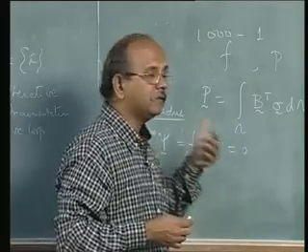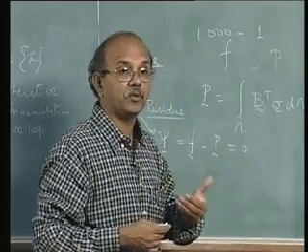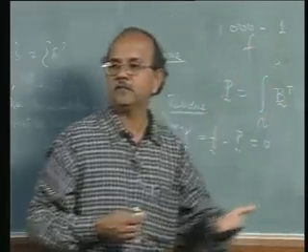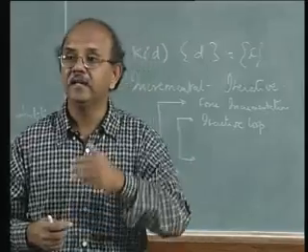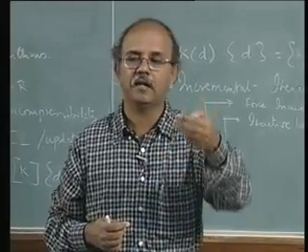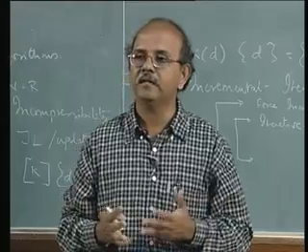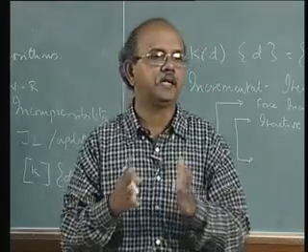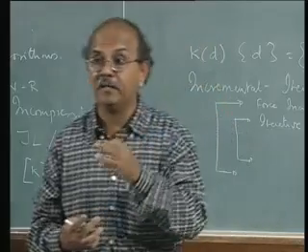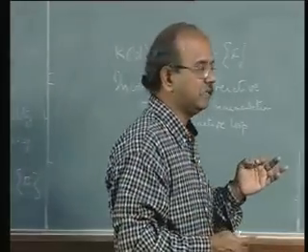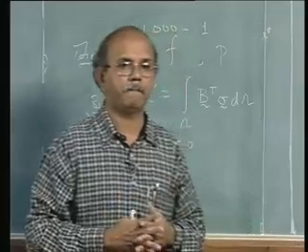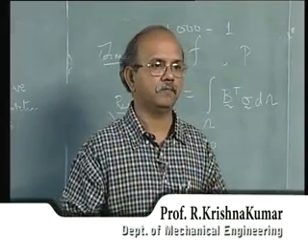So, when you say that you increment by 0.1 second, 10% of the load is applied in the first step. Instead of saying increment it by 100, second step increment the load by another 100 and so on, you say that let there be a time step with delta t equal to 0.1. It's much easier to handle. So whenever we talk about time in the static analysis, understand that they are used as a carrier for the force. That's all, nothing more to it.